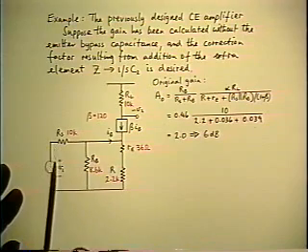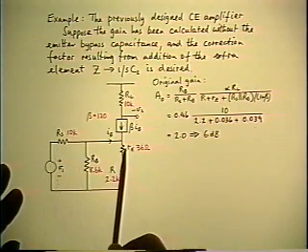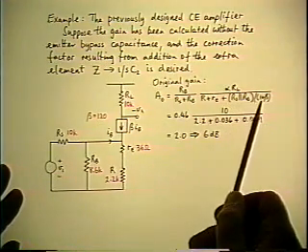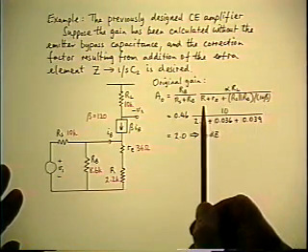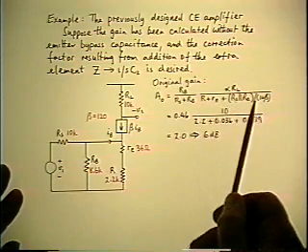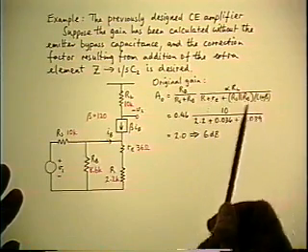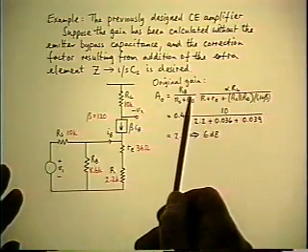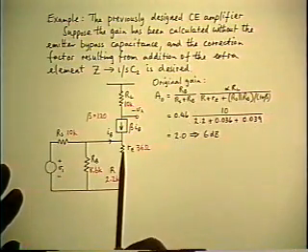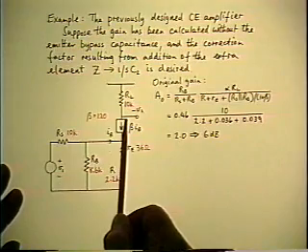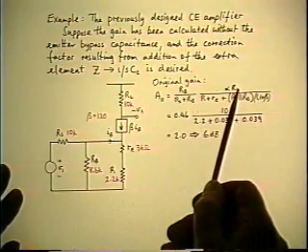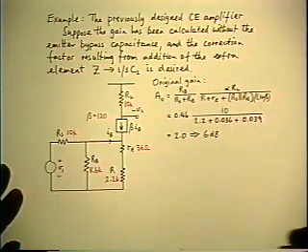This leaves the Thevenin equivalent voltage across RE in series with R, in series with the reflected base resistance. Therefore, determining the denominator of this expression, which gives you the emitter current as a function of the Thevenin voltage. Multiply the emitter current by alpha to give you the collector current, multiply the collector current by RL to give you the output voltage, and that's the end.